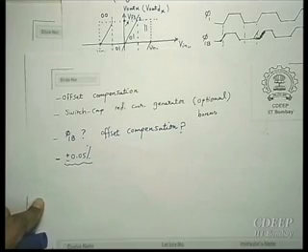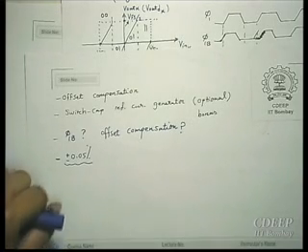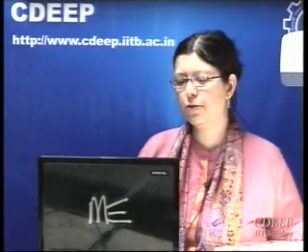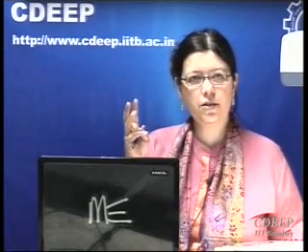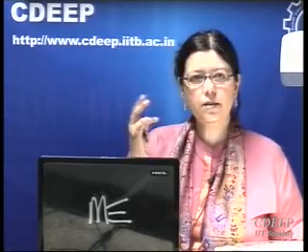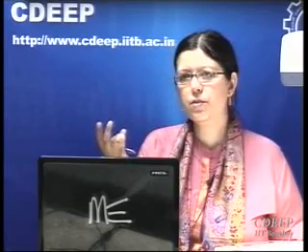However, what I want you to do is generate mismatches by some value which will give you almost similar characteristics to those given in this paper for SNR, SFDR. So we will do a reverse operation. Means that we want to see how much mismatch really can lead to this kind of characteristics. But you have two kinds of non-idealities. One is Opamp non-idealities, and of course Opamp offset that you will compensate. And then another non-ideality will be mismatch only. So just a small mismatch between these two capacitors, very small mismatch.